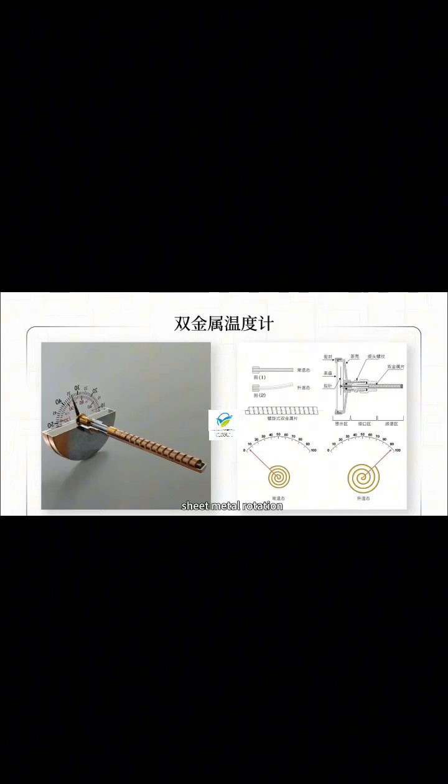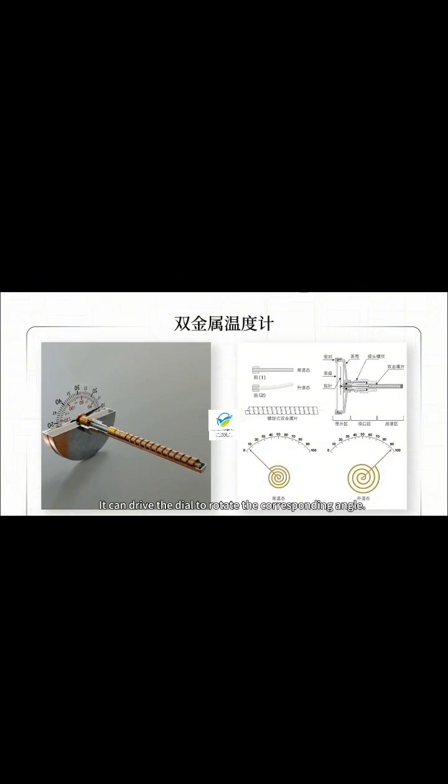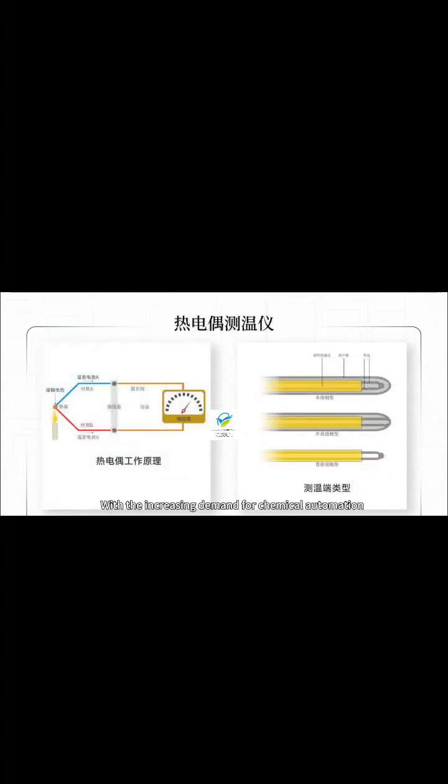It is made by filling a capillary tube inside a graduated glass rod with a working liquid. The liquid column rises due to the increase in temperature and volume expansion of the working liquid, which indicates the corresponding temperature value. The structure is simple and easy to use, but the material is easy to be damaged, and the data is not convenient to transmit remotely.